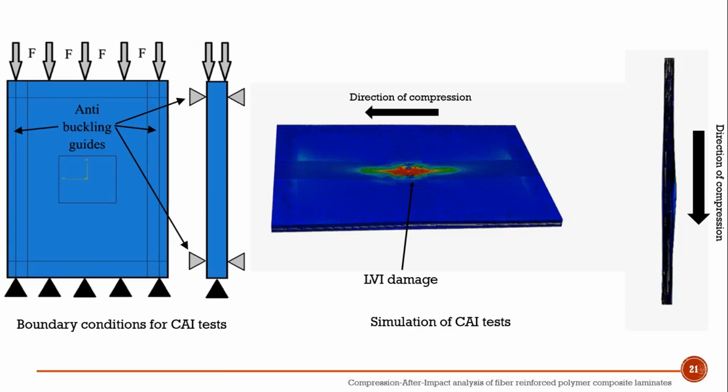You can go for vacuum bagging as well, or hand layup and then compression molding. We also have a machine with a huge pressure chamber, I forgot its name, but there are a number of methods by which you can do it. But for what I've shown here, we did it with hand layup, and then we went for compression molding.